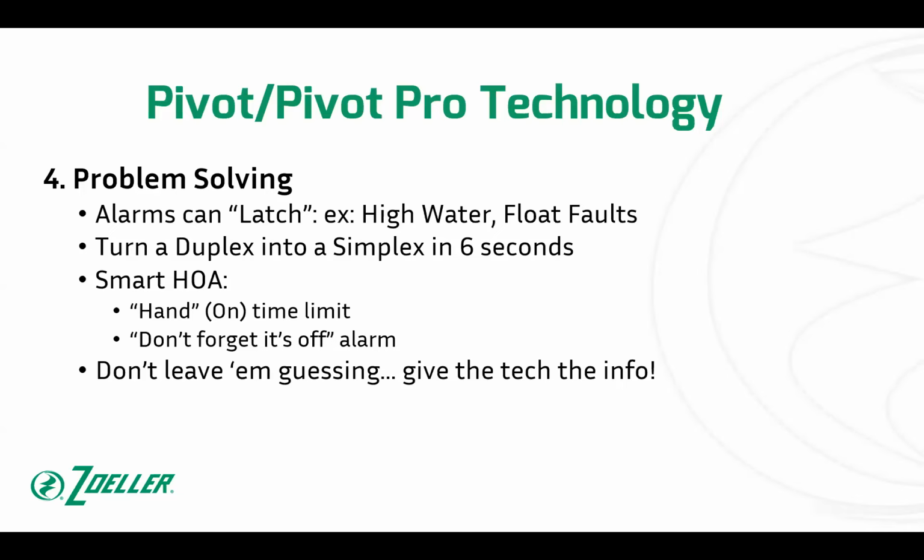So our alarm conditions, for the most part, default to latching, which means somebody's got to go up to the panel and acknowledge it. Well, if it's remote connected, you can do that remotely, but otherwise you would walk up to the panel, you would push the toggle on the outside of the panel down for 1 second to silence, or you hold it down for 3 seconds to clear.